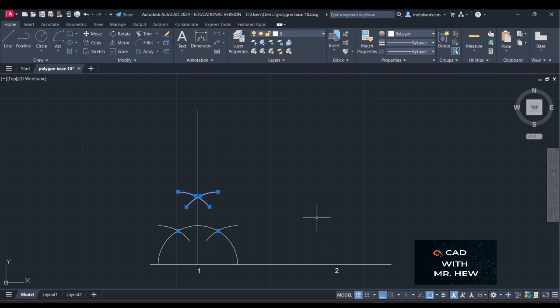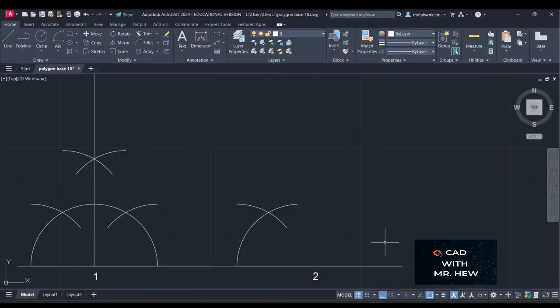What we're going to do next is construct a 60-degree angle at 2. As we indicated, we'll be constructing a 60-degree angle at the end of the line, at 2. So we put our compass point at 2. If we're using the traditional instruments, that would be the compass. You scribe an arc of any radius. You use the same radius and put the compass point right here, where the cursor is, and mark an arc to intersect the previous arc that you drew from 2.